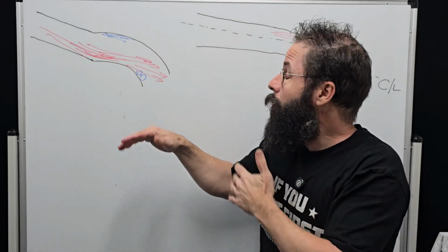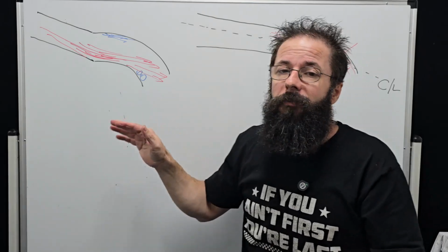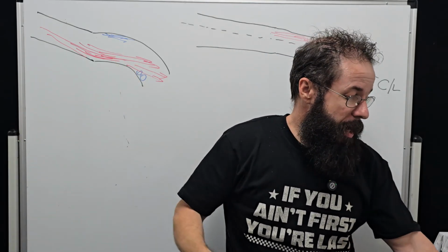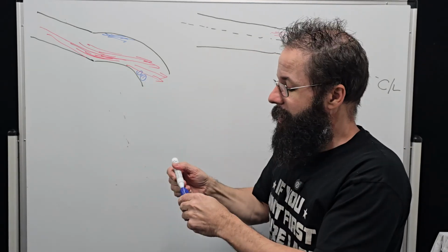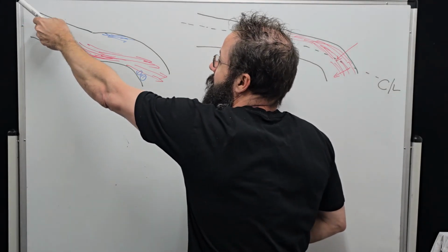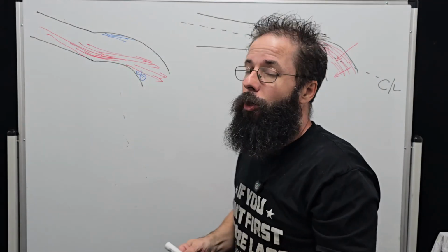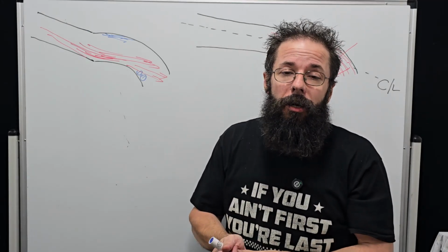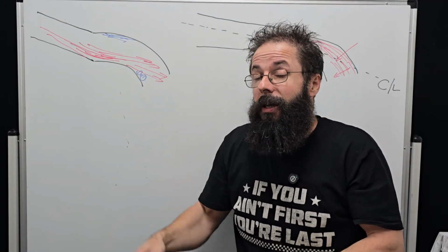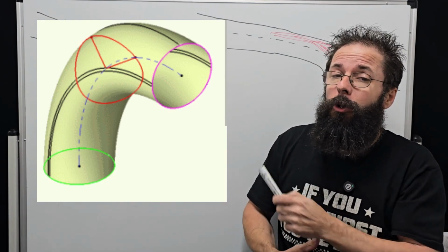So as the question was, this 100% affects downstream flow and the density gradient, and will cause separation sooner, because again, air will come in, it gets compressed along the floor, and then it wants to skip off the short turn. And again, we'll see that density gradient much as we're seeing it in the diagram I showed you of the bend. And here's an actual optimal bend. That's what it looks like.